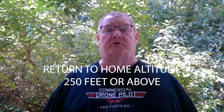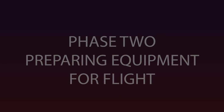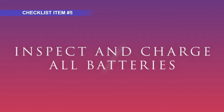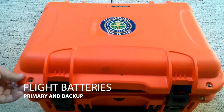So from that, we can ascertain that a return to home altitude of 250 feet or above will be sufficient to clear all of the obstacles that exist within the flight area. And that will allow us to move on to phase 2 of our checklist, preparing your equipment for flight. Number 5 on the checklist is to inspect and charge all batteries. The first battery we'll look at is the flight battery.